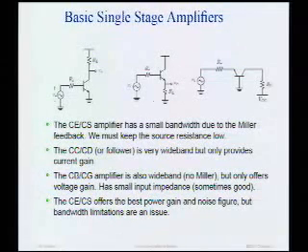So its power gain is certainly going to be less than a common source amplifier. What about the bandwidth of a common source amplifier? Well, the bandwidth is very good. It's a very wideband stage, and that's because there's no Miller multiplication.